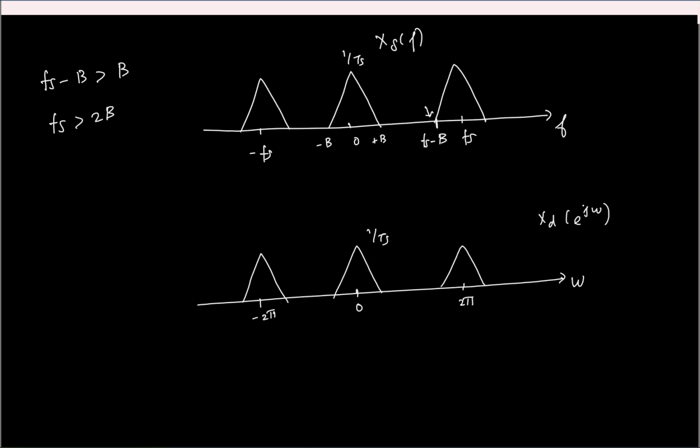And this frequency, which is twice the signal bandwidth, is often called the Nyquist rate. That's basically the minimum frequency at which Nyquist recommended us to sample any signal, right? Great. So, okay, now let's look at the same effect in time domain also quickly.